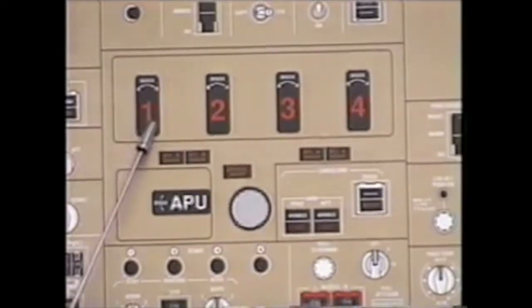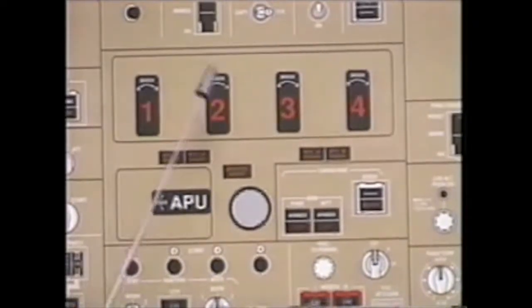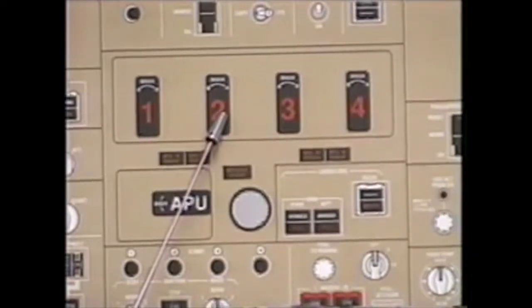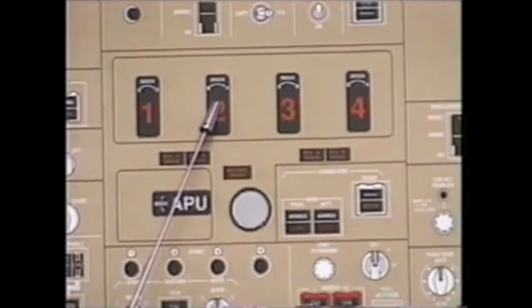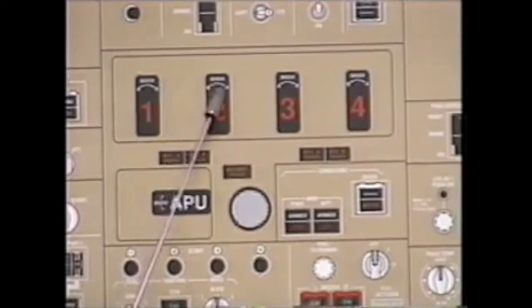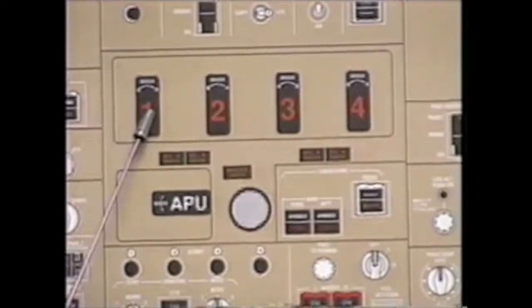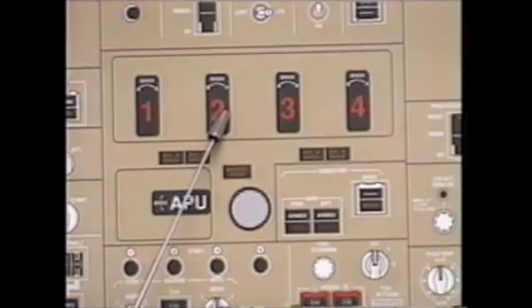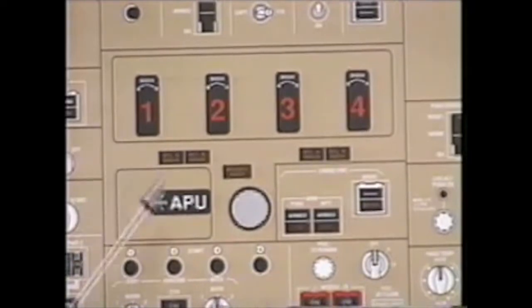If you discharge one bottle into one engine, you can discharge the other bottle into the other engine by rotating the handle in the same direction. If you notice, the control handle shows left on engine 1, for example, is A, left on engine 2 is B. If you were to pigeon toe the fire handles, either toe in or toe out, that would discharge the same bottle. APU, only one bottle for the APU. Once that bottle is discharged to the APU, there are no other fire bottles available.